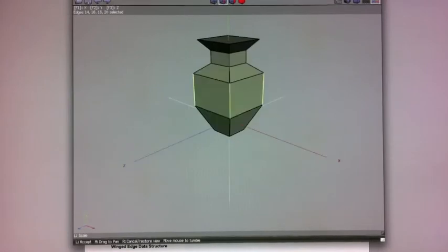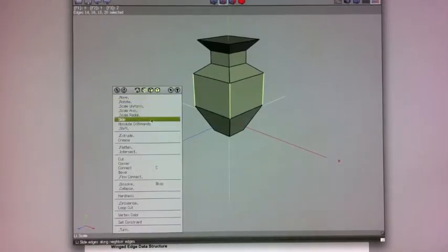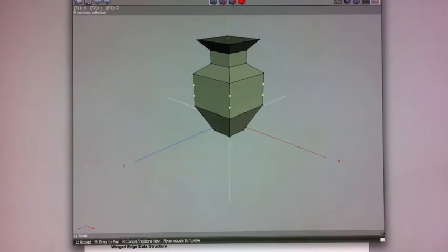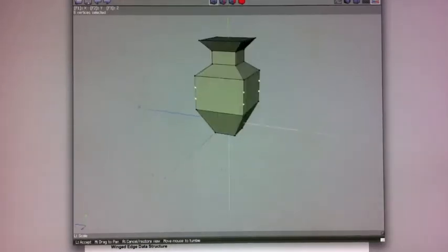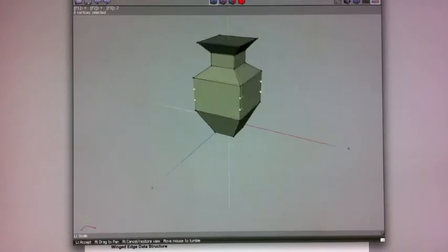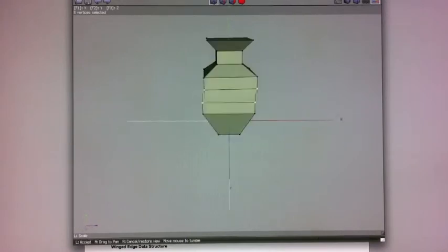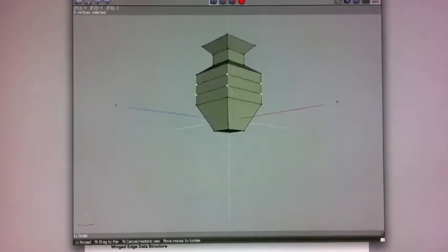The most useful thing here is you can do all of what you did already, but you can also cut the edges, and you have a couple of options like 2, 3, 4, or 5, or you can select any number you want. So let's do 3 for the moment, and you can see it added all the vertices, but they are not connected, so we can't really do much with them. If we press C or connect here, it's going to connect them, and it's really good.